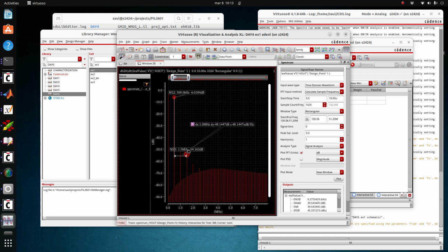There are always more poles than zeros, so the loop gain will decrease at higher frequencies and eventually reach zero, and then there will not be loop gain. So the higher the frequency, the lower the loop gain, and we can naturally understand that the correction of the nonlinearities will not be as effective as at low frequencies. But now this is working at 500 kilohertz.